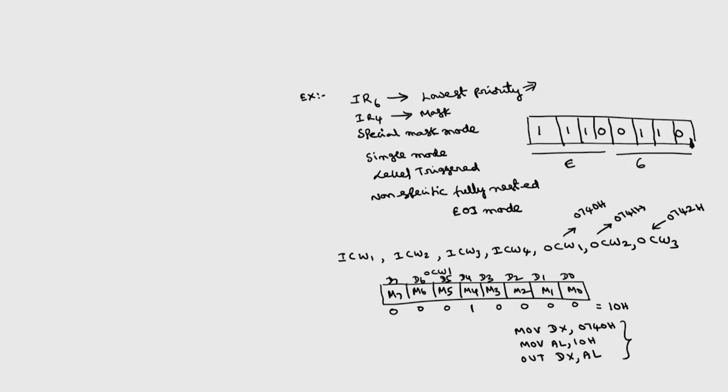The corresponding instructions for this will be MOV DX, 0741H, MOV AL, E6H, then OUT DX, AL.